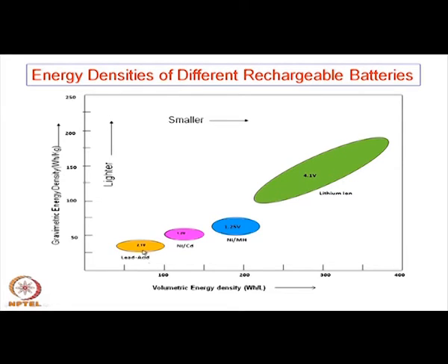This first one is about the lithium ion battery, compared to the lead acid battery, which was used extensively in earlier days. These are insertion compounds, in which lithium can be intercalated or inserted into the structure of most solid materials. Today there are two active materials here, the anode and the cathode, both lithium intercalated compounds. One is very simply graphite.